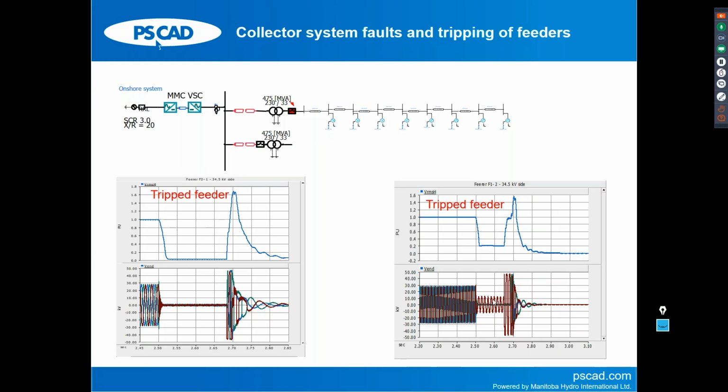And similarly, in the response on the right-hand side, you can see the overvoltage lasts for a little bit of time. So we may have to again go to the vendor and ask them to review this, and maybe they can adjust their overvoltage trip settings, right? Settings where the inverter controls tell the inverter to actually back off and bring the voltage down may be a settable parameter.